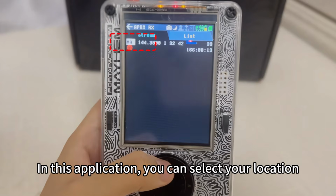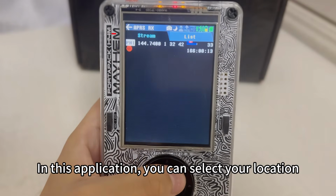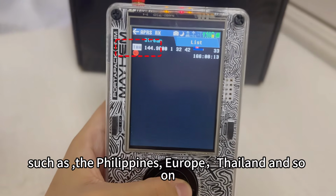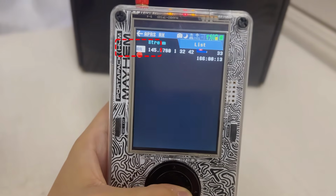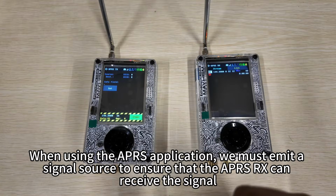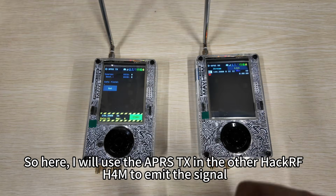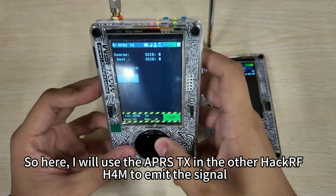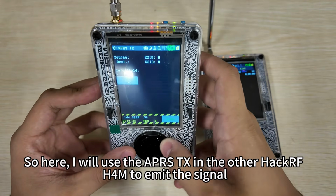APRS. In this application, you can select your location, such as the Philippines, Europe, Thailand, and so on. Here, we still have frequency, AMP, LNA, VGA, signal bar, and volume. When using the APRS application, we must emit a signal source to ensure that the APRS RX can receive the signal. So here, I will use the APRS TX in the other HackRF H4M to emit the signal.